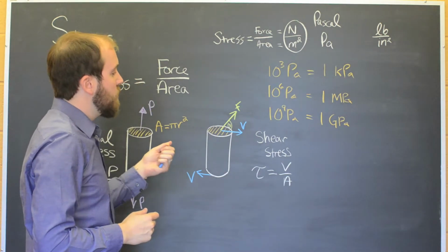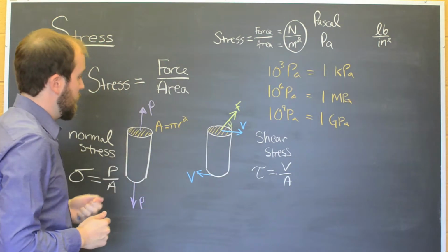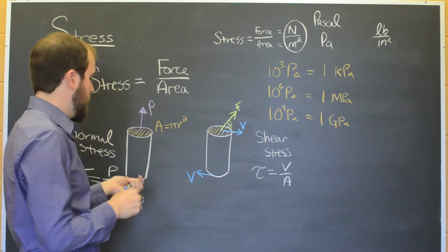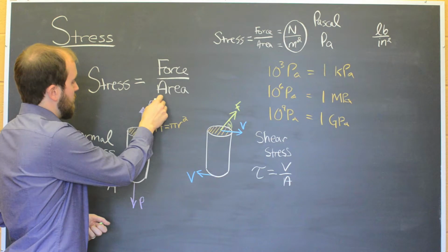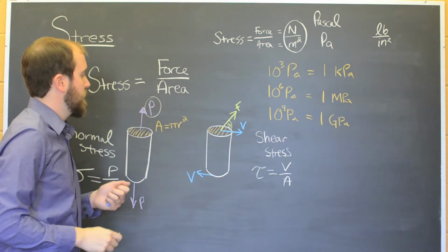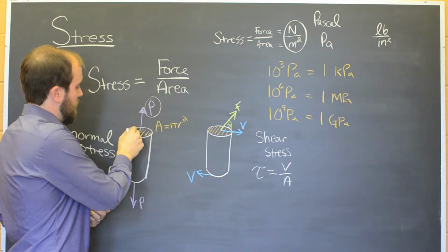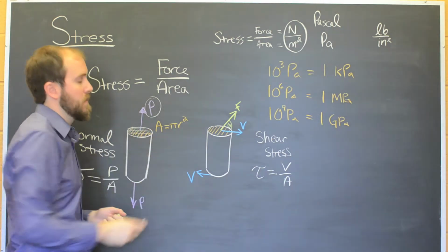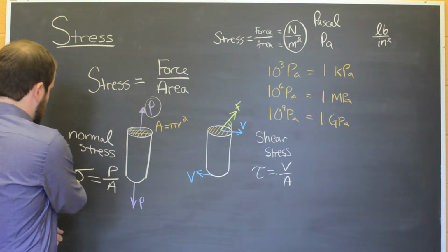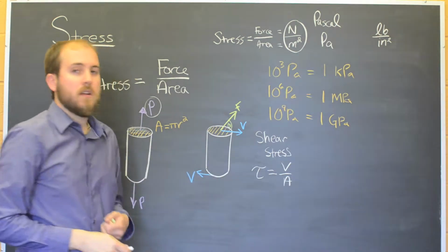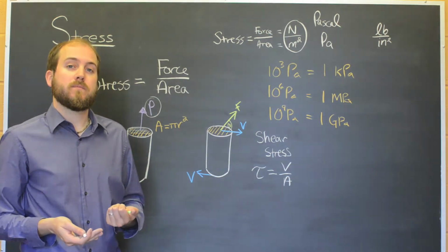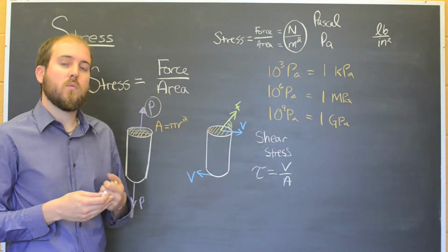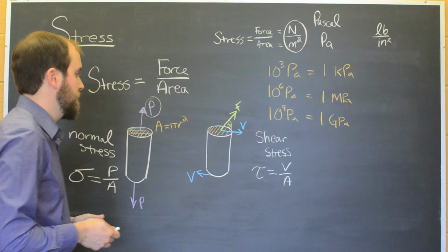So there's one important assumption that we made here in describing these stresses that we'll come back to and revisit later throughout the course. And that assumption is, we've assumed that this force is being evenly distributed across this entire cross-section here. And so what we're actually describing with sigma and tau are average stresses. And as I said, we'll come back to understanding when this assumption breaks down.